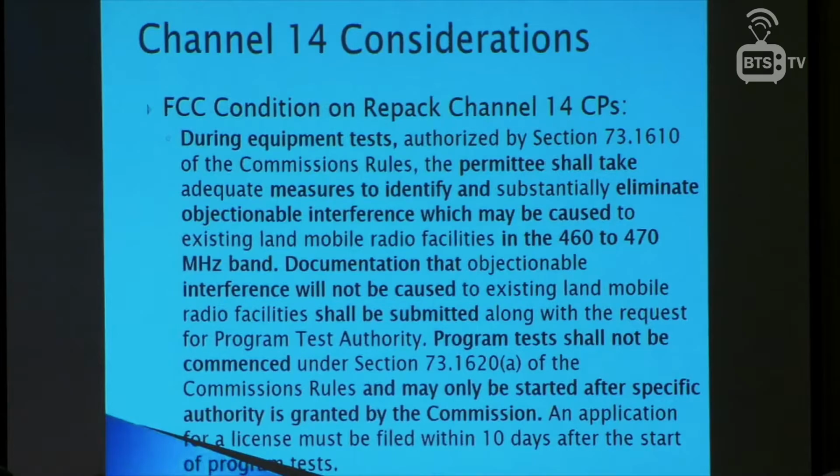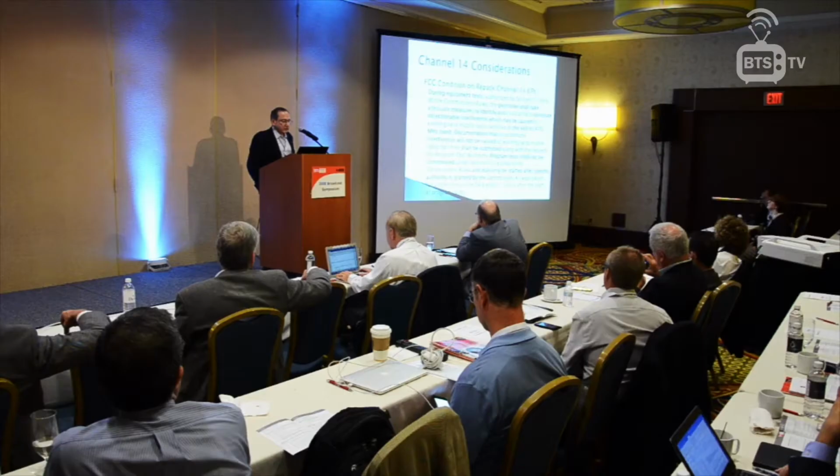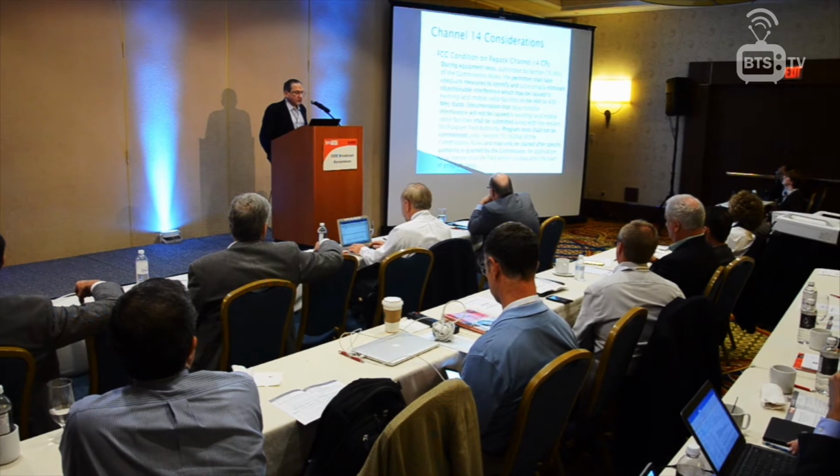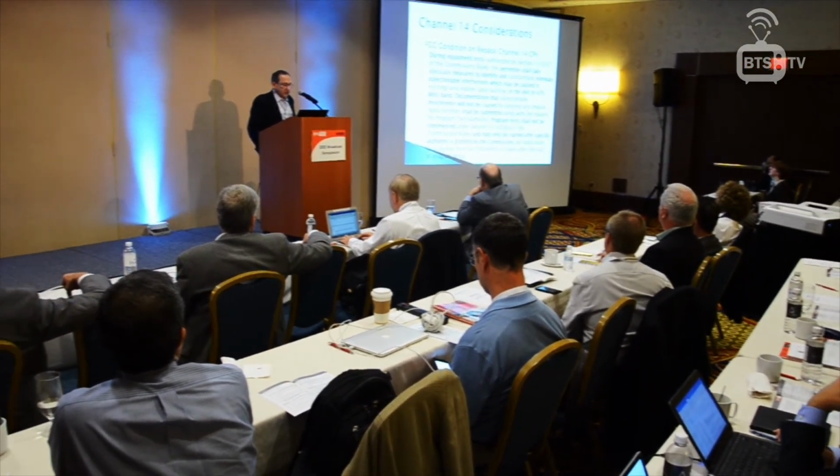That's always been there, but it's never been worded the way it is on current construction permits. If you look at the condition on a Repack Channel 14 construction permit, it says, and I'm going to read the parts that I bolded here, during equipment tests, permittee shall take measures to identify and eliminate objectionable interference, which may be caused in the 460 to 470 megahertz band.